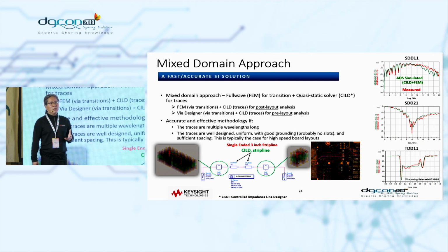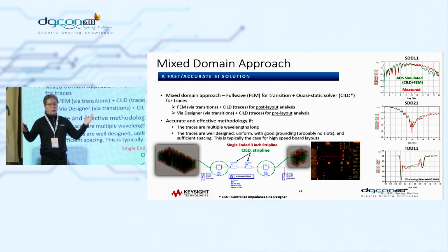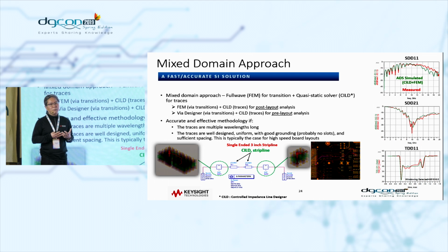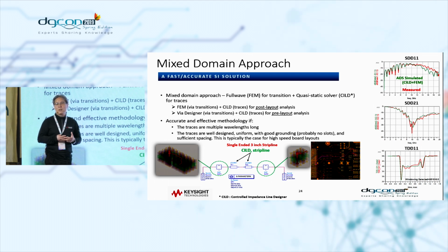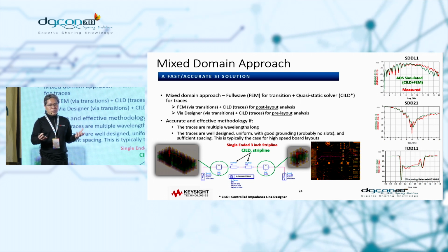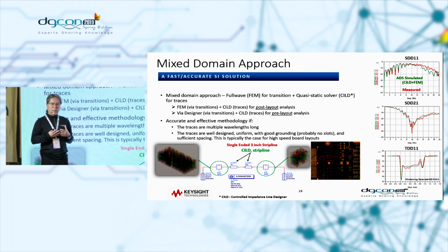Once again, when we have a certain interconnect that comes with a transmission line and via, all the transition issues or problems coming out from the channel are coming from the via, not the transmission line. So sometimes you don't even need to simulate the transmission lines. It's because most of the designs just follow the design rule.